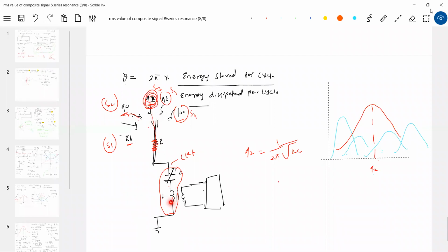Then the one which has maximum current only, I'm going to filter it out. Then that will be amplified and given to us. We are able to listen to only that station. What happens if you listen to all 5 programs at a time? I think it'll become noise, no? In a classroom, if all 5 students shout out at a time, we call it noise. So what should I do? I should request any 4 students to stop talking, and let only one talk. The circuit is called a selective circuit. With the help of this series resonance circuit, I'm able to select a desired set